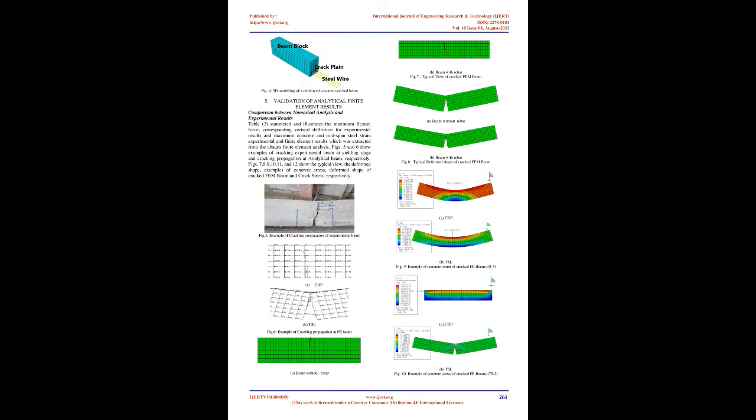In the current study, the concrete damage plasticity model, CDP, and damage for traction separation laws, TSL, have been used to model the concrete behavior, because it provides a general ability for modeling concrete matrix in all kinds of structures. It uses the notion of isotropic elasticity in combination with isotropic tensile and compressive plasticity to represent the behavior of concrete. It can model concrete reinforcement elements with defined reinforcing rebar. Comparison between the fracture methods and its crack extension.